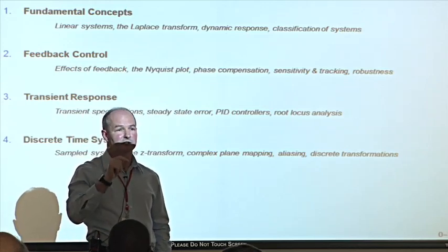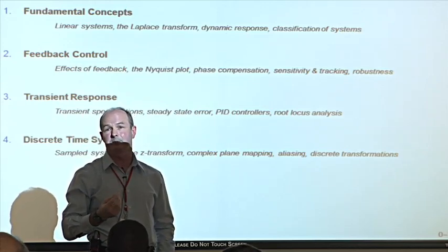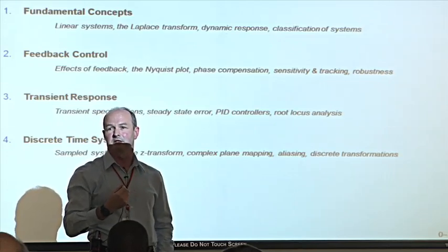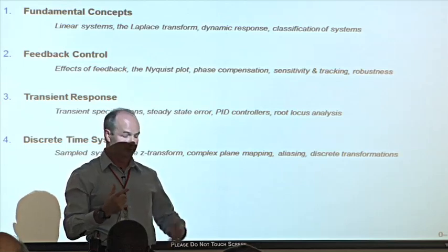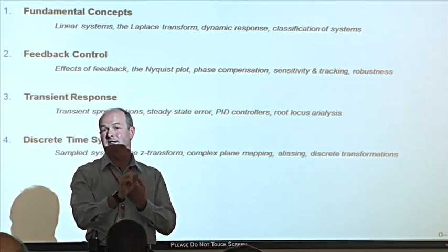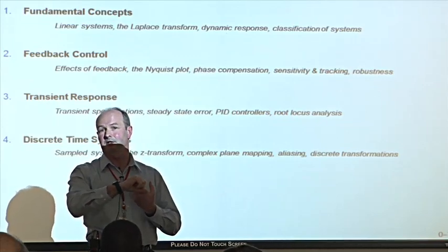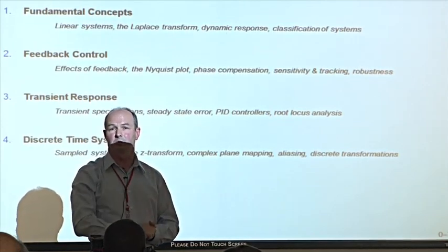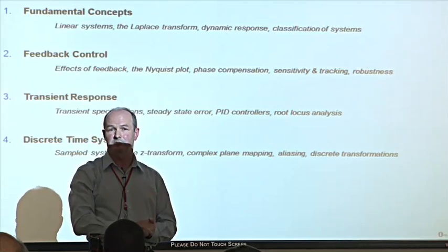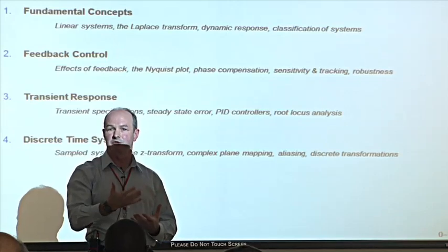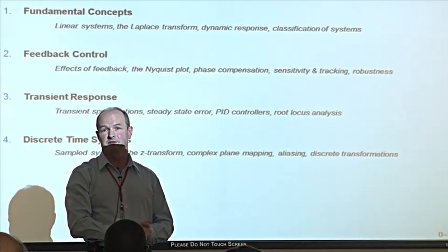You apply some kind of discontinuous input, such as a step, and then you analyze the output, the response to that. Now, the response I'll show you shortly comprises 2 different parts, one of which is the steady state part, and the other is called the transient part. The transient part for a stable system will decay, it'll die away. But the properties of the transient part capture the dynamics of the system. So by tuning those properties, we're tuning the performance of the system.